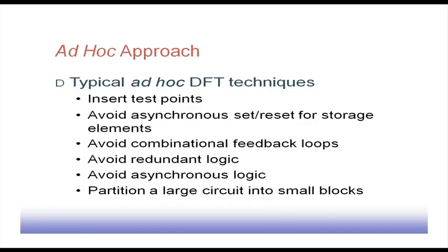Then asynchronous logic. If we can ignore asynchronous logic, then we know that the entire operation is synchronous with some clock signal, so my testing can be concentrated on the individual clock transitions only. Scan cell shifting and all that can be done easily, but an asynchronous system does not have a clock. As a result, it becomes difficult to control the overall test session.